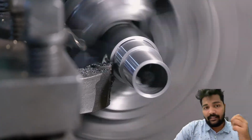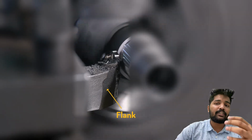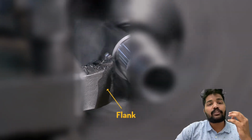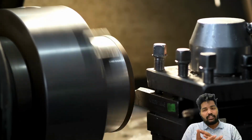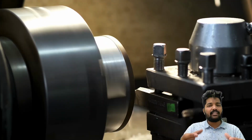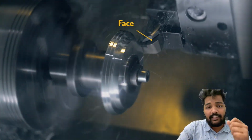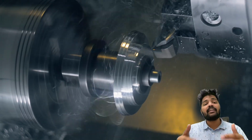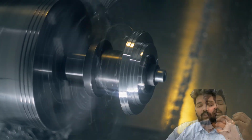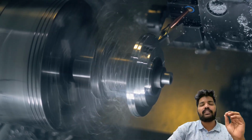Second, we have the flank. Now the flank refers to the surface below and adjacent to the cutting edge. It plays a crucial role in guiding the chip flow during the entire cutting process, ensuring efficient chip evacuation and preventing chip jamming. Third, we have the face. The face is a surface on which the chips slide as they are being removed from the workpiece, preventing built-up edges and ensuring a clean surface finish.